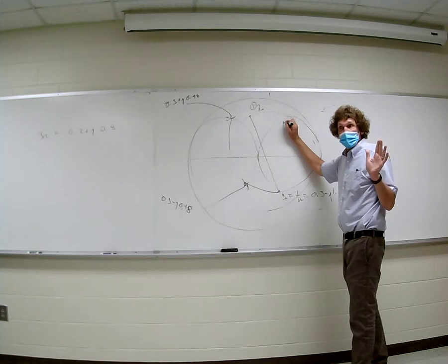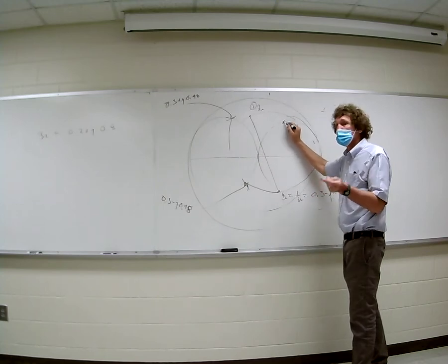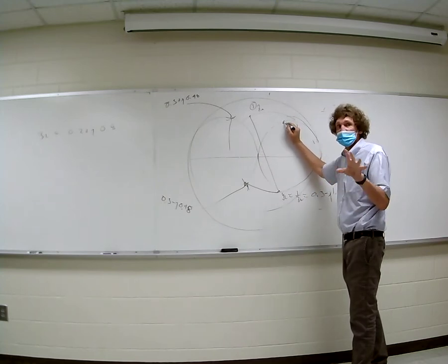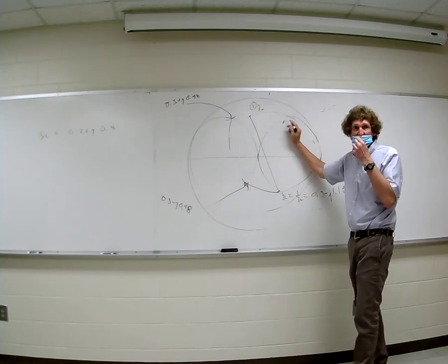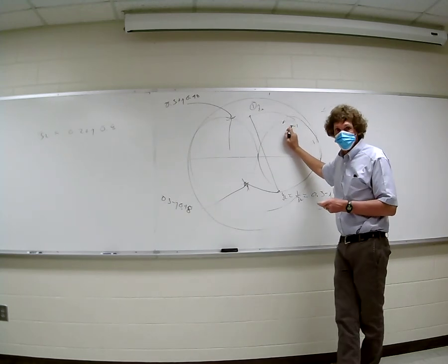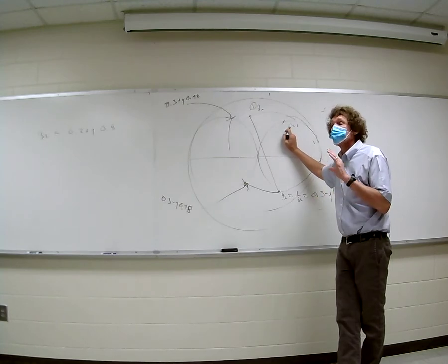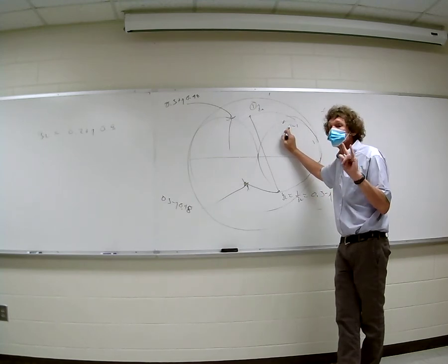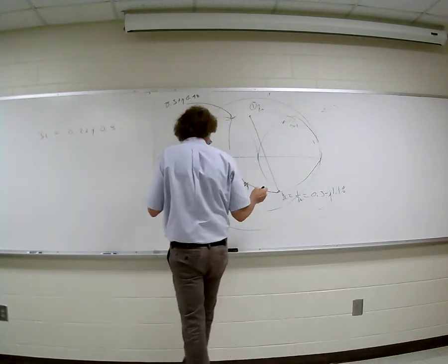Now listen, now we're in the impedance domain, and we want to get here, so we have to add a minus j. That's a capacitor. Do y'all hear me? That means I would be adding a capacitor in the impedance domain. I don't want to do that because it blocks DC. And I can tell you right now, I want something that doesn't block DC. In other words, an inductor would be in series and a capacitor in parallel. Y'all follow me? So this point won't work if I want that.